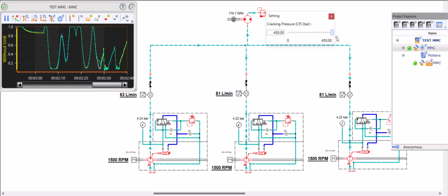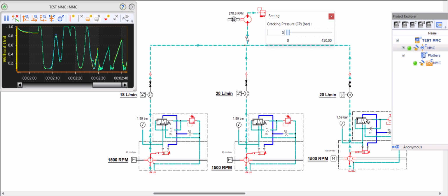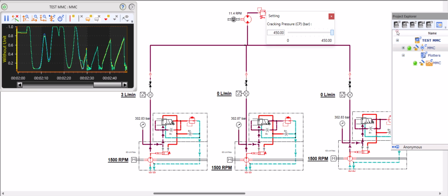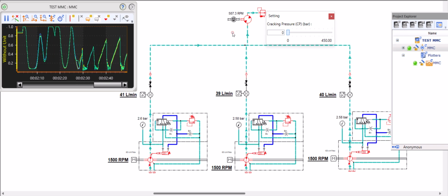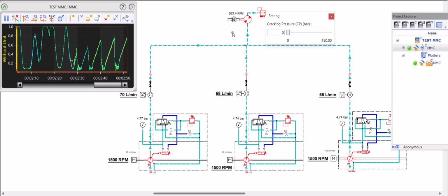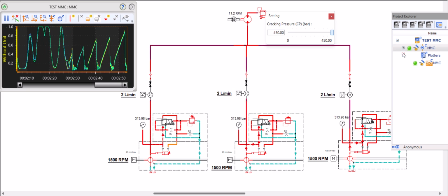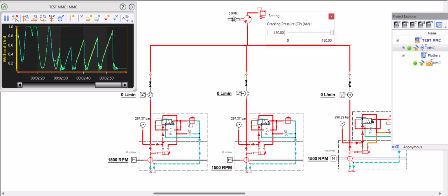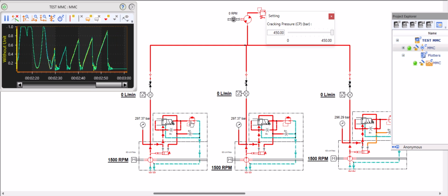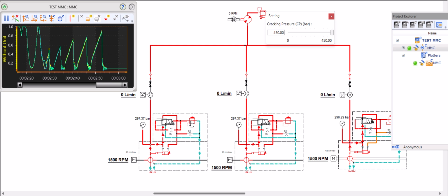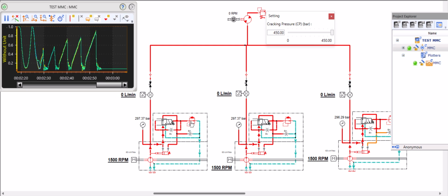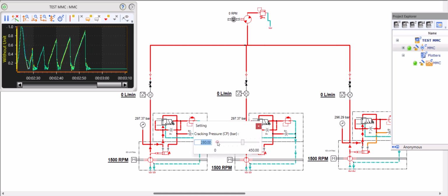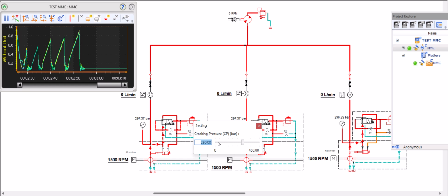And you can see the behavior in the rapid change. There are rapid fluctuations in the demand system. This is very common in an industrial scenario. Of the experiment, we are going to do the ideal thing. Typically, since this is set through a spring, it is not possible humanly to set it at the same value. This error may be up to 3 to 4 bar. For this experiment, we will take it at 5 bar.